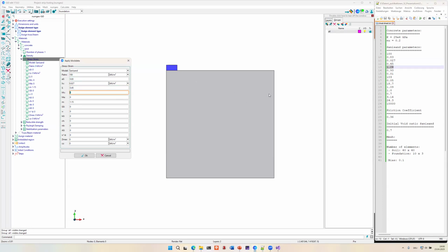Then we have to specify the friction angle related parameters like MC and ME. We then give the parameter for M, which is the opening of the cone for the yield surface. Then the parameters G0 and the Poisson ratio. And then the other parameters, which are pure fitting parameters, determining the material behavior under various different loading conditions. So I will just copy them in there.